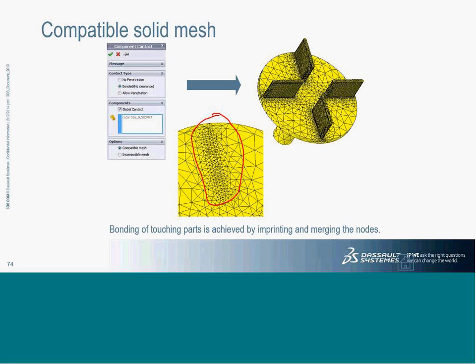However, there are cases wherein this small body on the top, say, this particular plate I highlight over here, is very small, and the bottom plate is very huge. The bottom link is very huge. In such cases, you see meshing failure. The mesh may not be created because it is not able to achieve the continuity that we are expecting in a compatible mesh. In such cases, incompatible mesh can do a better job.